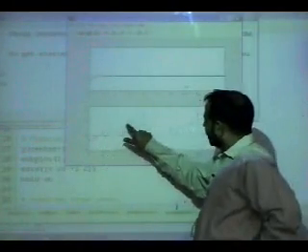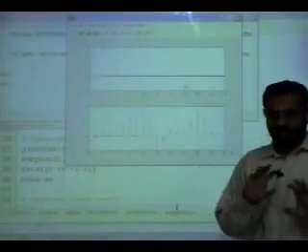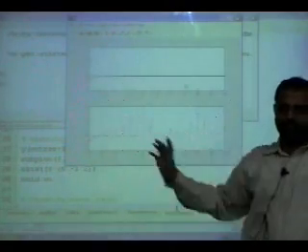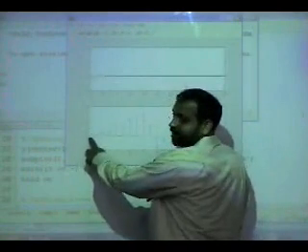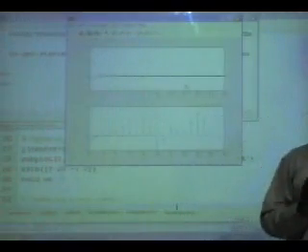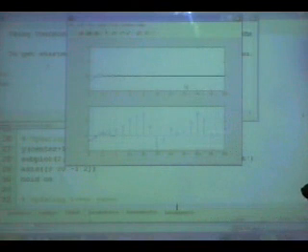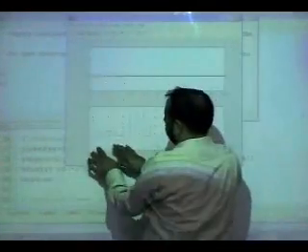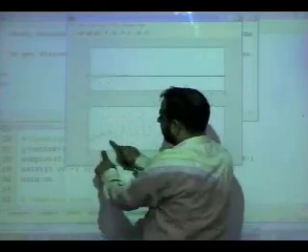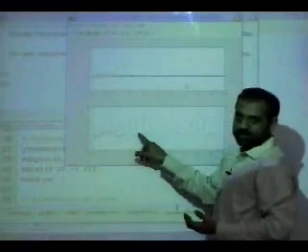These are the samples. Okay? Now at the location of every sample you remove the sample and make a sinc. Yeah, that's what we are saying reconstruction is. At the location of every sample you make a sinc. Okay? So this is the sinc which you make here. This is the sinc. Okay? Then for this you make another sinc, and you keep adding those sincs, and I'm showing all the sincs here and their cumulative effect here. So I'm adding all of them together and showing that here.